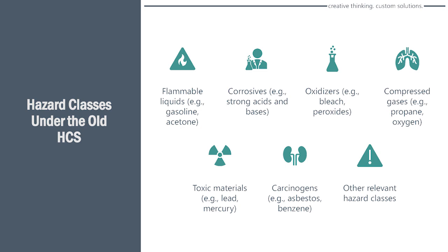Because the chemical is not going to be called corrosive chemical number 4. The biggest example I can think of is we had a set of environmentally friendly chemicals that we used for cleaning at one of my jobs. When the chemicals were diluted to the proper concentration and handed out to the employees to use, yes, they were very environmentally friendly, but they came in a concentrate. So a lot of those would be corrosive or flammable or an oxidizer when they were in their concentrated state. That was something that we had to talk to people about and train them on, because there's a big difference in something that's 50% ammonia and something that's 2% ammonia. So that was one of the things that we always had to address under the hazard classes.